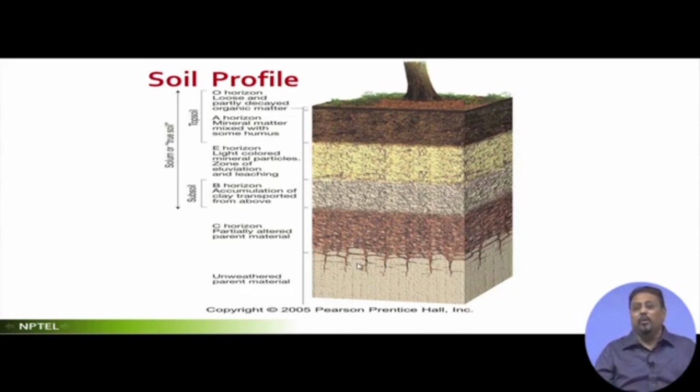So what happens is, whenever you are trying to find out soil stability, in such cases, for geotechnical investigation, you break the soil and then you take it to the lab, and then you try to find out the stability of this. It is meaningless, because by breaking it, you have already added air into it, and the particles' stability, the structural bondage, you have broken.